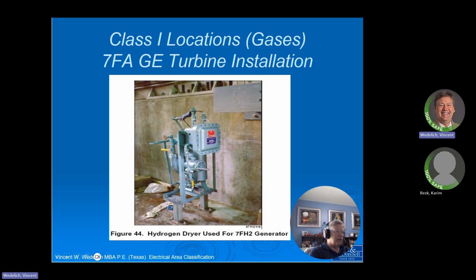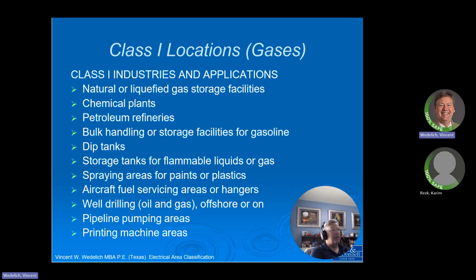So if I was going in there and I started looking at this design, I'd flag that electrical connection right there. It looks like a little flexible connection. It should have a special type of connection. I'd flag that single phase motor. And obviously they're still doing construction, so there are other things. It has to be rated for that environment.